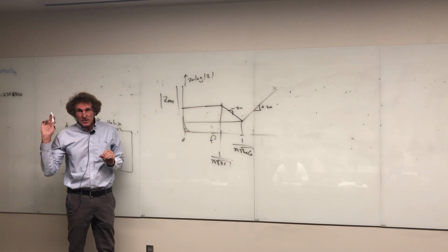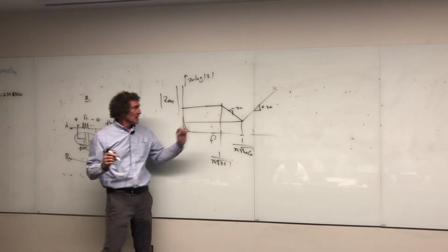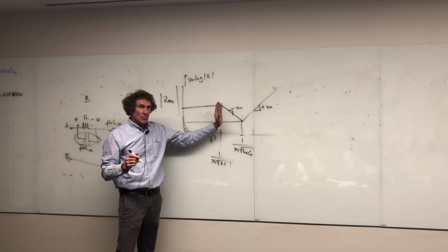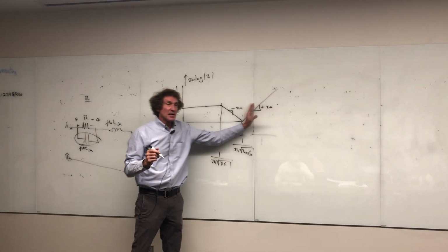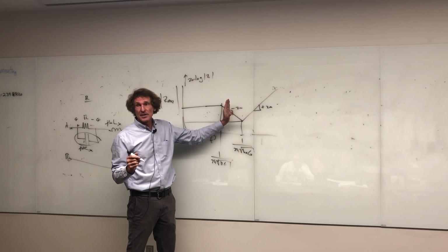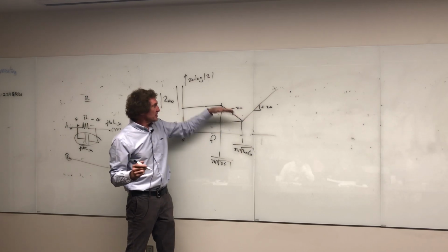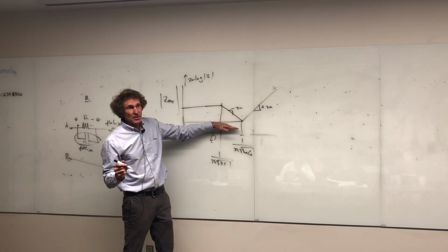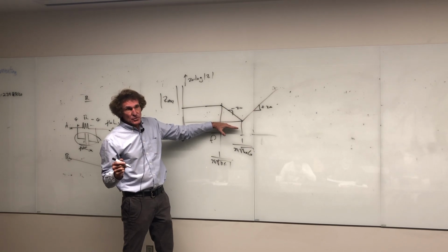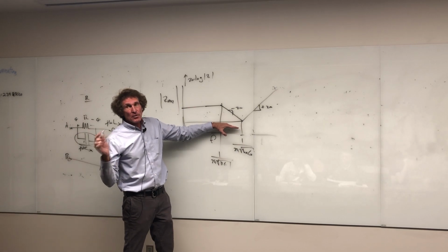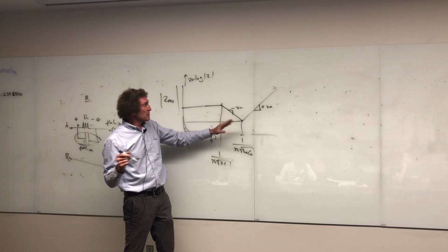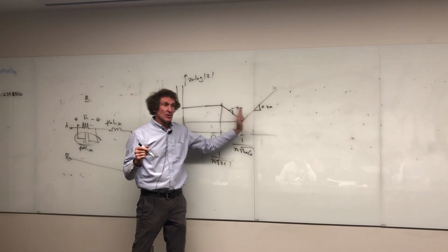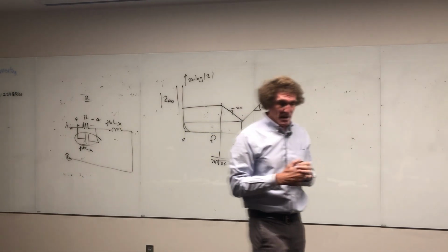But when you see this, something really jumps out at you. If I'm operating with my resistor up in this domain, it doesn't look like it should. It's way out of bounds, and this could be 2 or 3 orders of magnitude. We don't know. That means whenever you're designing something with resistors, and there are possibilities of higher frequency components, you have to take a careful look at the effect of that. I'll leave it there. All right, see you Monday.